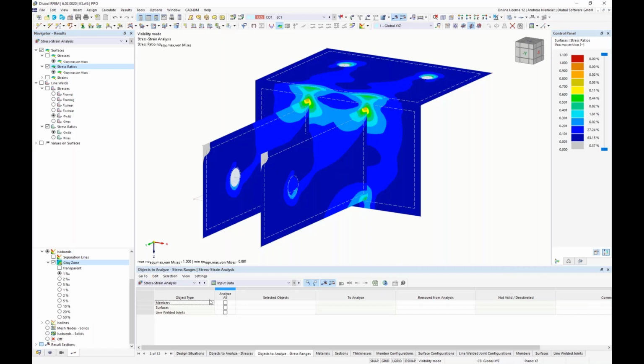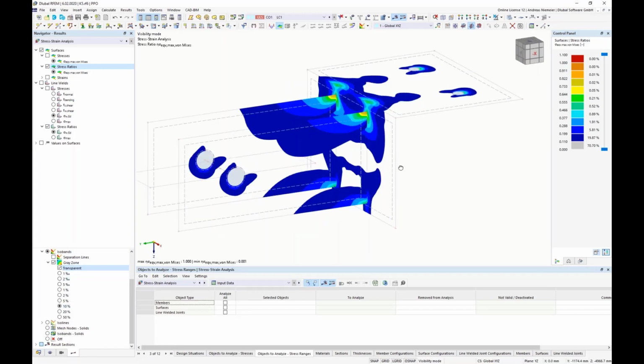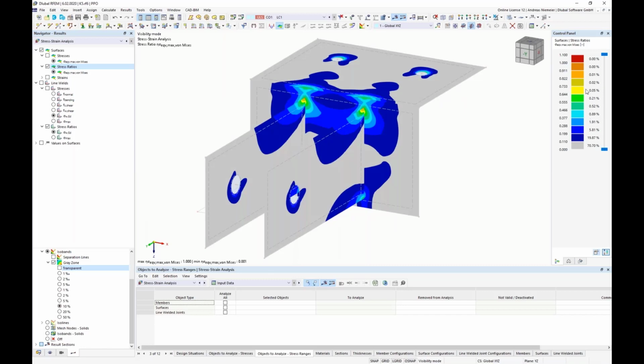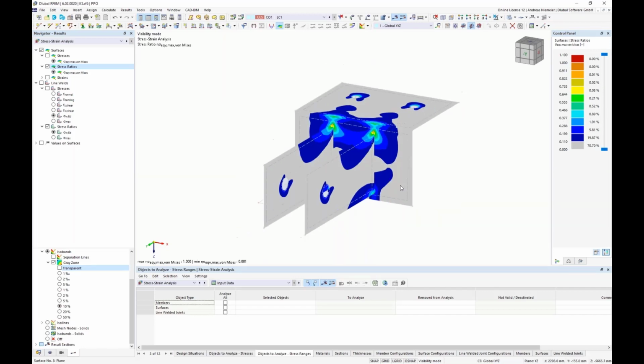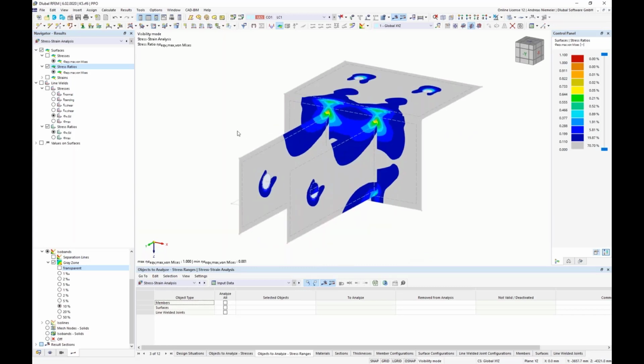You can say here, please hide the 1 promille of uninteresting part, or maybe 5 promille, or maybe 10%. Then you see, okay, it hides now 10% of the uninteresting stress, what is not so close to the limit, and the rest will be visualized, and then you can make a nice picture without playing with the colored panel and see directly where it's interesting. And you see, okay, interesting is here's the load introduction, here's the load introduction, here's the load overtake from this to this element. And now let's find a good placement in space and print the picture to report,